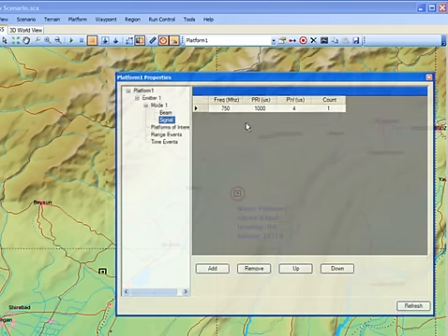Also, we have a signal. This is the pulse table right here, showing you the signals at 750 megahertz. I'll go ahead and make that 1250. The PRI or PRF, if you prefer, is available, and the pulse width is 4 microseconds and a count of 1. That means it'll produce one of these pulses and then wrap to the next one around.